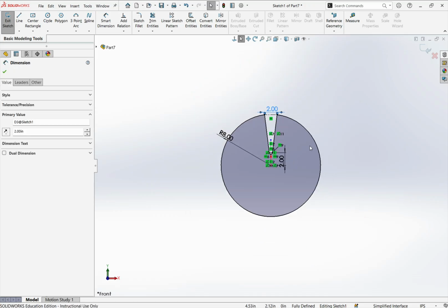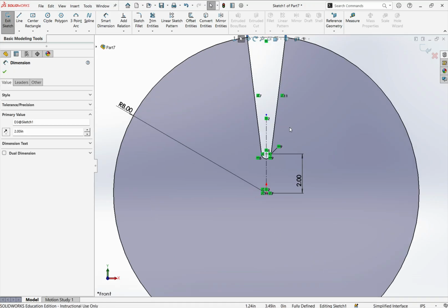Okay, so when I was creating the sketch, the first thing I did was I selected a center point circle. Remember, there's perimeter circle and center point circle. Selected the origin. So again, here are my relationships. This would be the one that makes the point that I added with respect to the origin. The other coincidents are actually with respect to other features up top here.